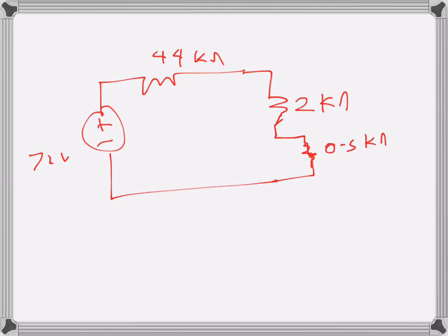So it's a pretty high one actually. An ammeter with this range of internal resistance is not suitable to measure current through such a low resistance, because this is pretty comparable, just 1/4. If the resistance was say 50 kilo ohms, then the current would be quite close.